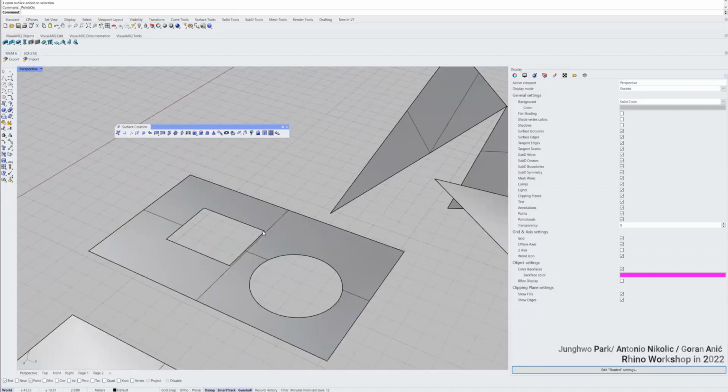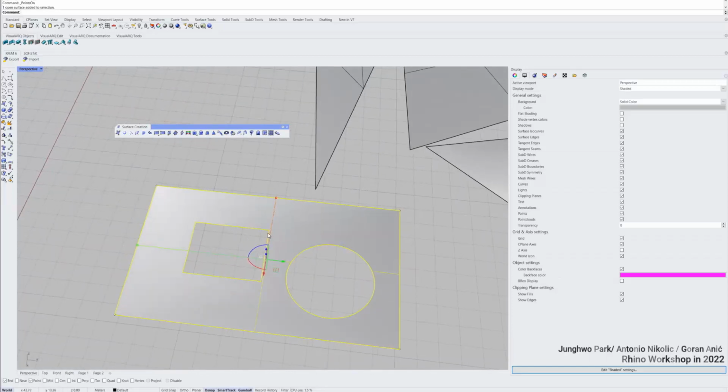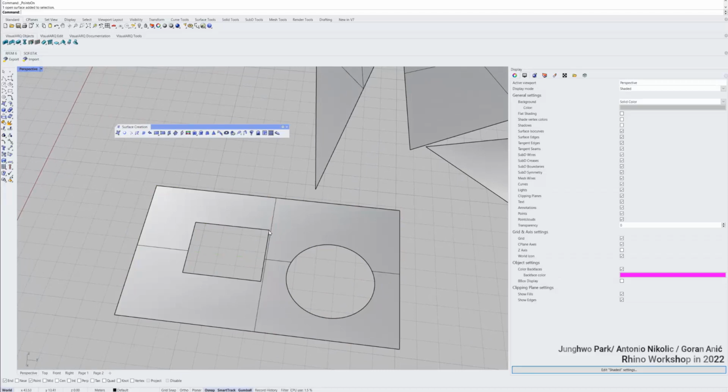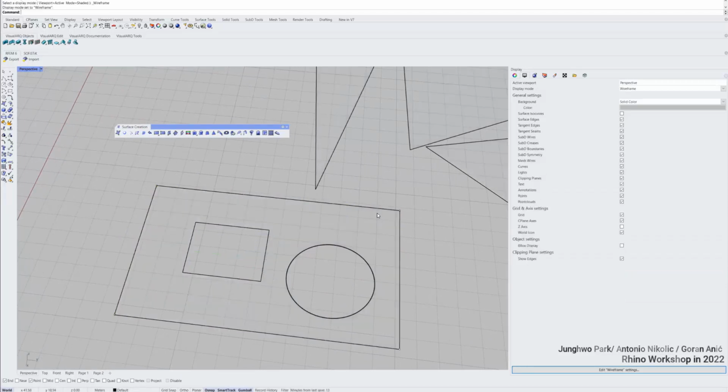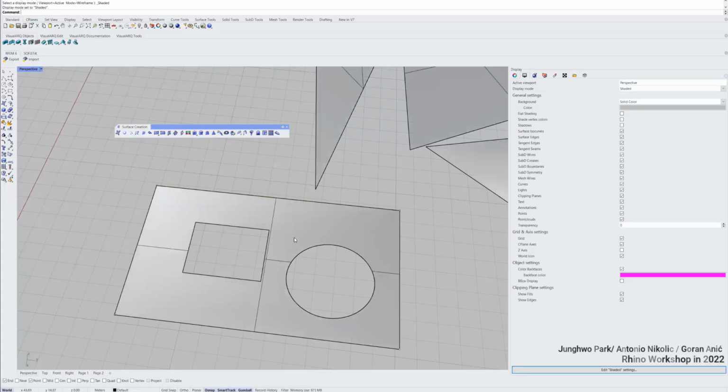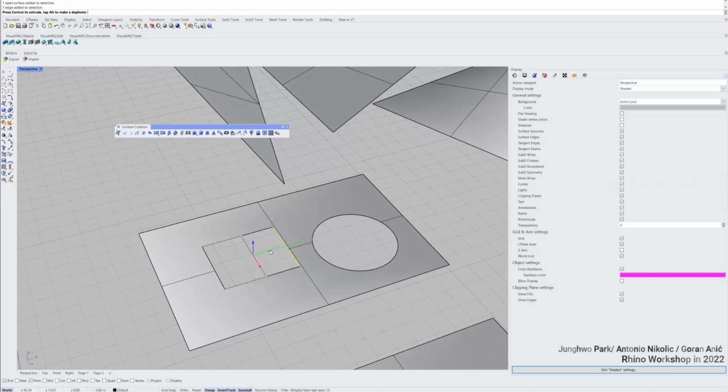And also you can press F10 again. In this case, it doesn't show the vertices of this opening area. Even though you press F10, it only shows these 4 points. But if you hold your Control and Shift keys at the same time, and then you click the edge line, you can change it, or you can select points, and you can also edit it.